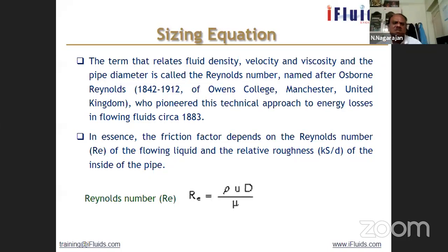So if you enter 6-inch, 2 elbows, 1 T, 1 reducer, the program automatically determines the equivalent length, by the API table linked with it, and the straight length we put in. These are simple, straightforward calculations, and nobody does any hand calculation. It's just entering the values and getting the results. Most companies have their own in-house line sizing.